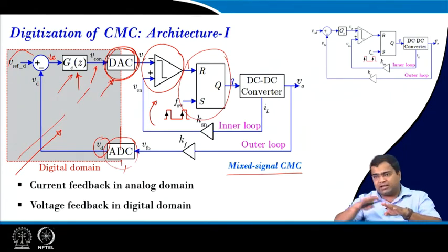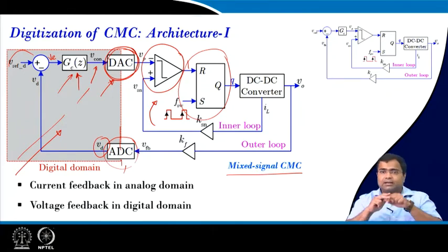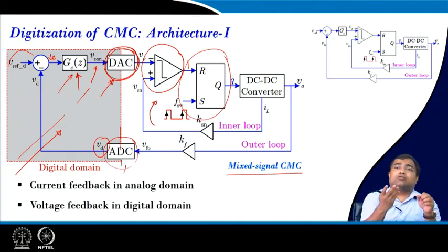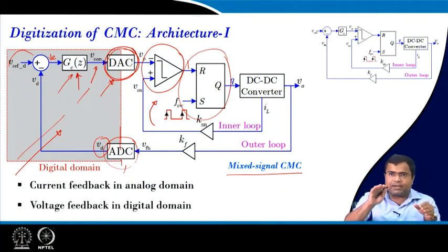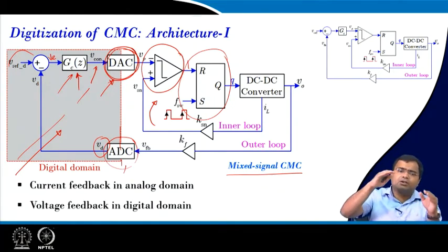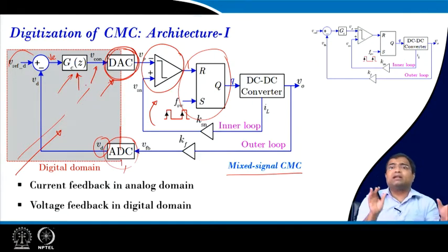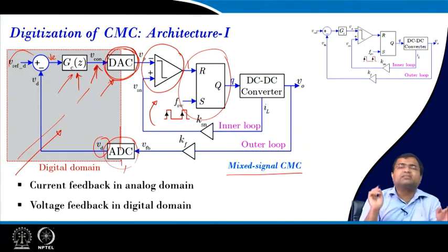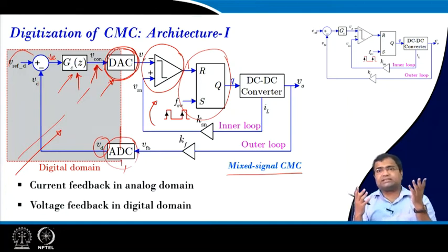So you can actually keep the actual limit inductor current by using an external command. That means you want to command that I want to limit the current for 4 ampere or 10 ampere or 15 ampere. So this is much flexible by just a command line, because this is ultimately a number which you can adjust through a register.